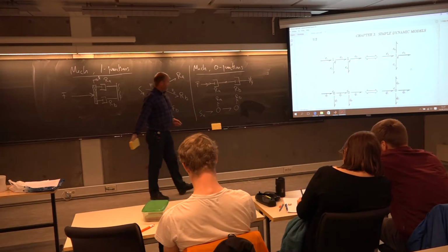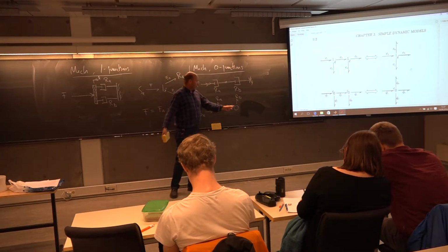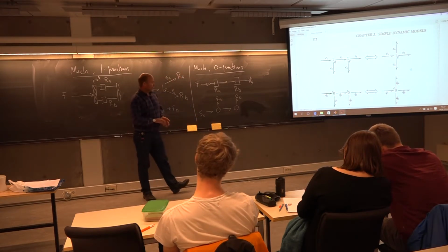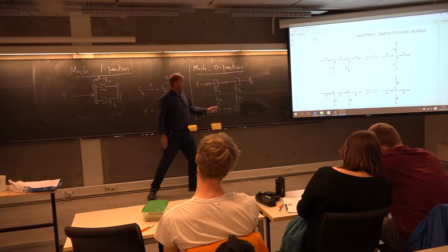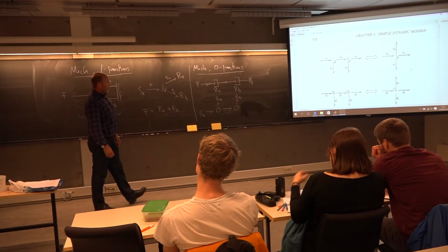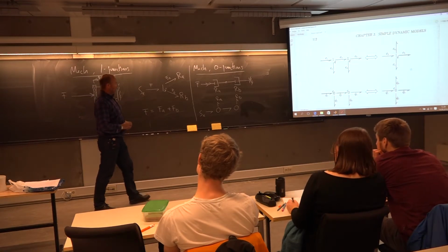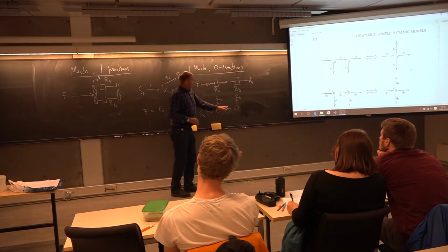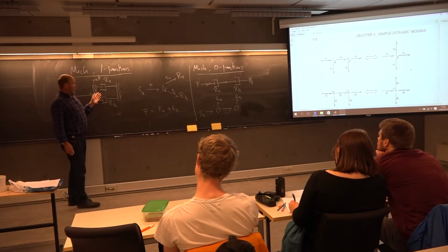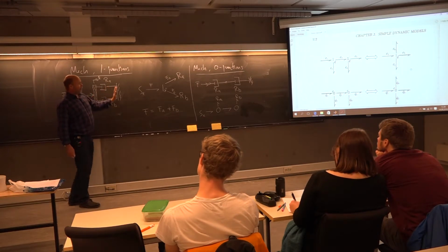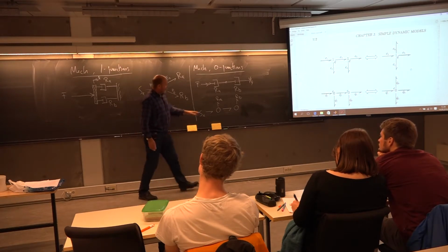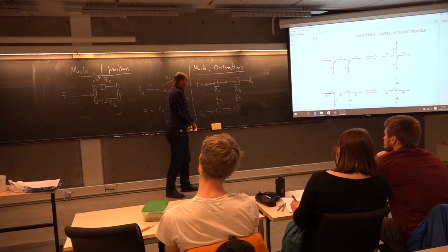Then the bond graph is left with these two zeros. And when you have two zeros next to each other, you can actually just join them. That will be the same as just using one single zero junction. The same we could have done in such a problem if we had another one junction connected here somewhere. We could just have joined them.